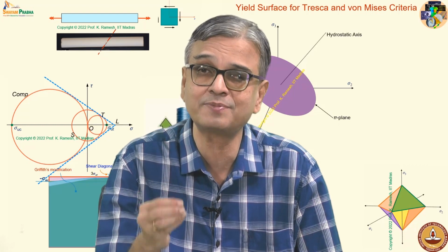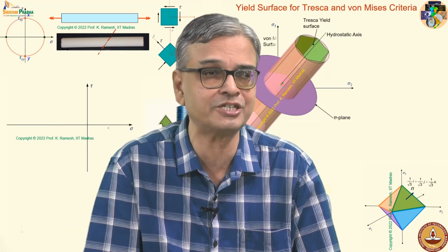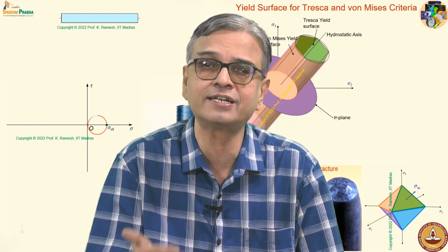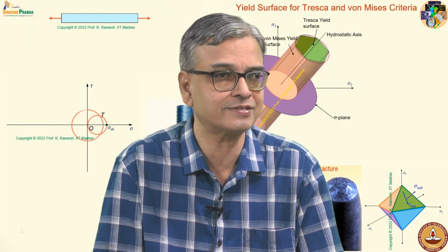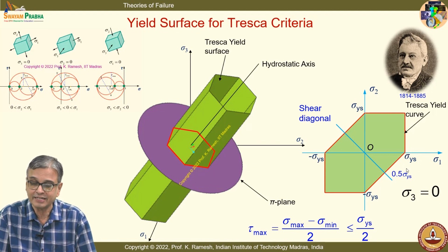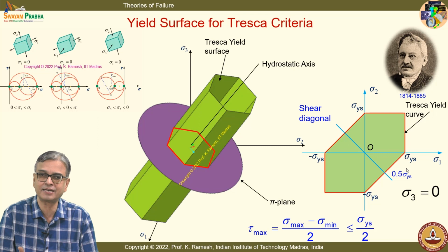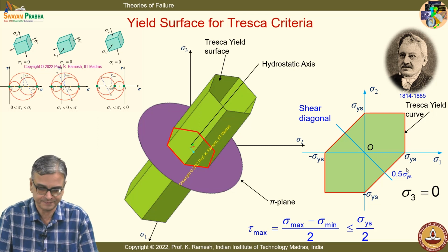The tension test is the simplest test that you can do, even that is costly, that is not cheap, because you have to prepare the specimen as per ASTM standards. You should have a calibrated testing machine and follow all the procedure and evaluate the parameters. And what we do is we exploit what we have got in the carefully done tension test in terms of hypotheses or proposals. That is how failure can occur. Later on we will also see experimental verification of these theories.